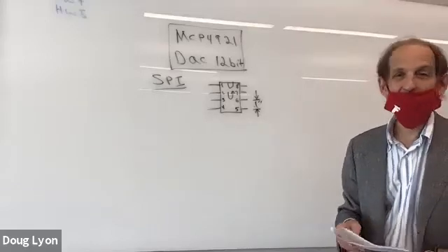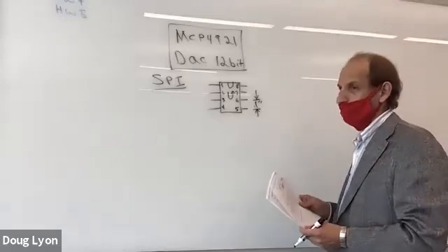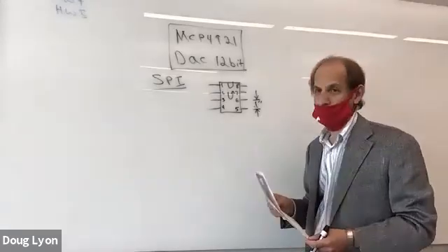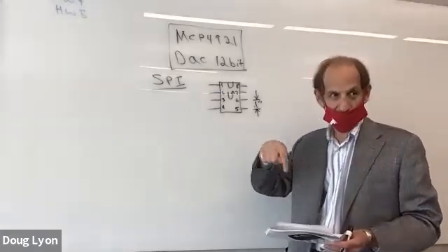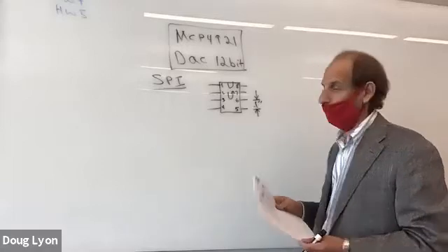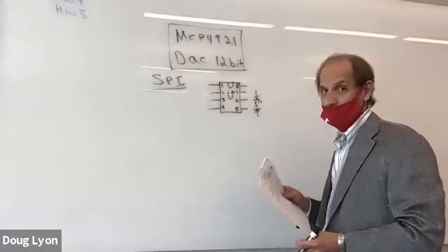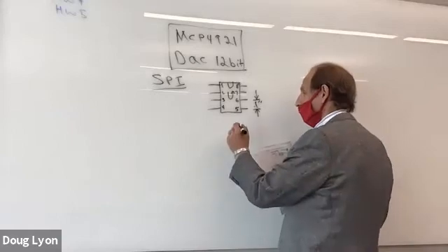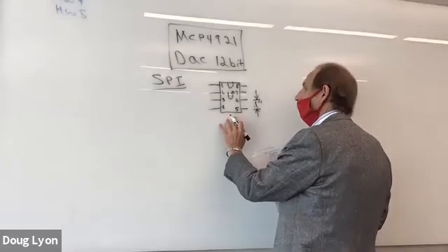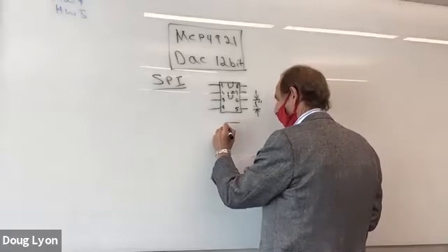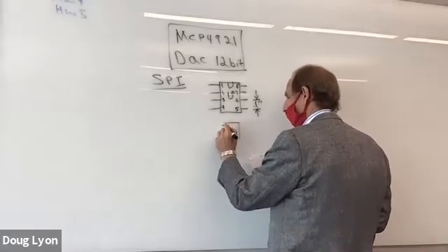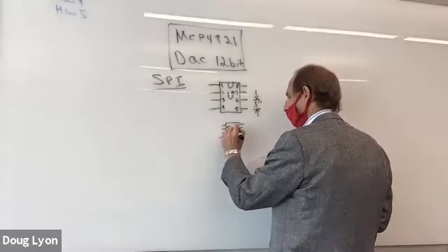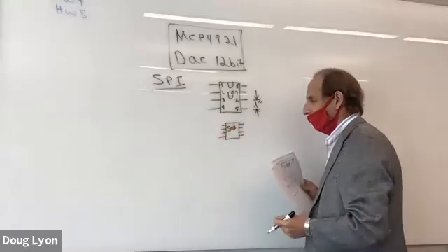Drill bits wear out fast. And the drill bits wear out because you're drilling through fiberglass and epoxy, and the drill bits break, and you have a thing called run out where the little drill bit wanders, and you have bad holes, and it's just terrible. And then you don't get plated throughs if it's not a professional bore. So what you do is you switch this out for something with an identical pin out, but with a different outline. They call it SO8, for small outline 8 pin.